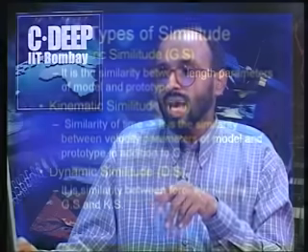With respect to the model and the prototype, or the real field problem, how we can have the similarity or similitude, this kinematic similitude gives. So the kinematic similitude is the similarity of time. The last one is the dynamic similitude.